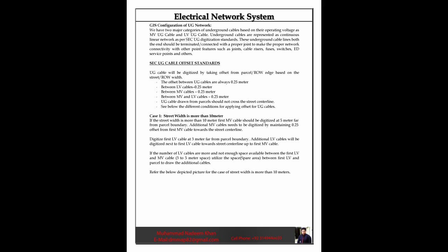If the number of LV cables is more and not enough space is available between the first LV and MV cable, utilize the spare area, 3 to 5 meter space, between the first LV and parcel to draw the additional cables. Refer to the picture depicted below for the case of street width more than 10 meters.